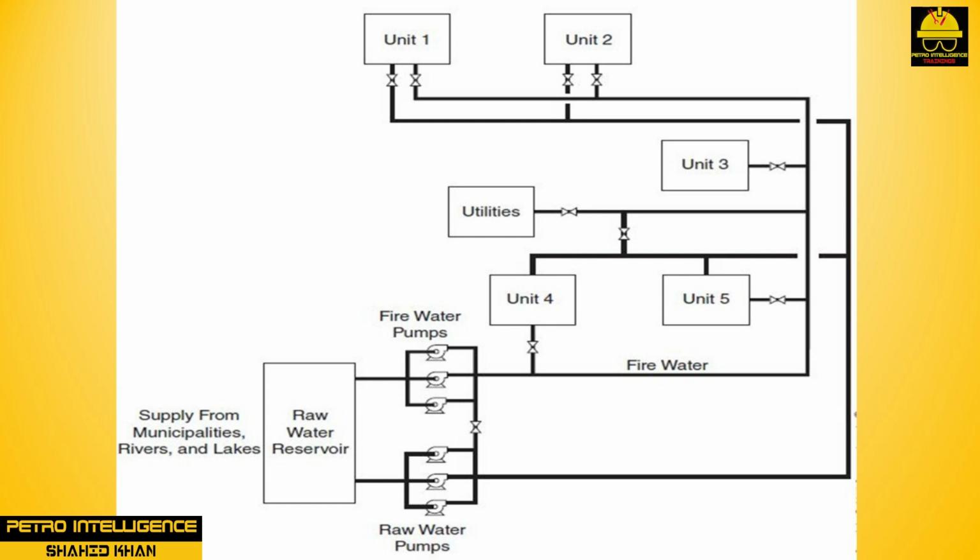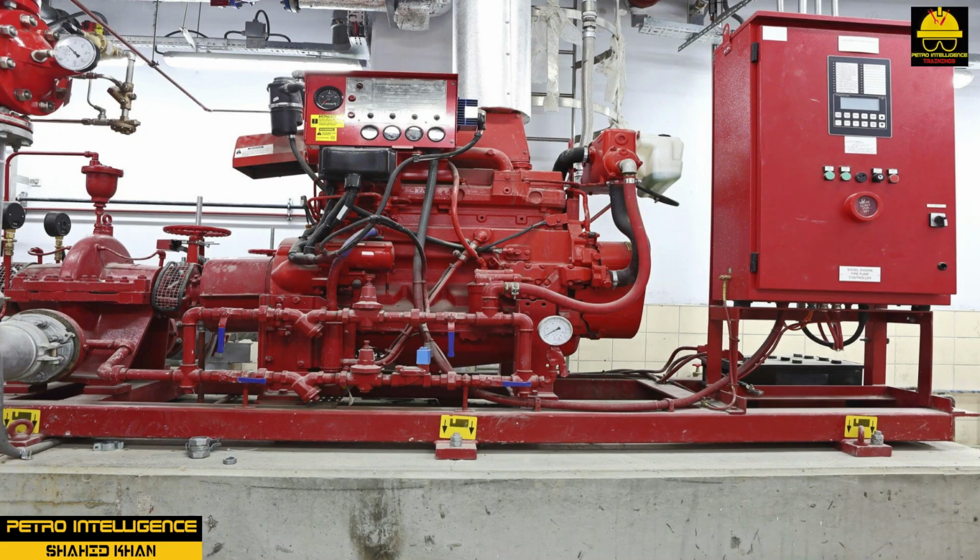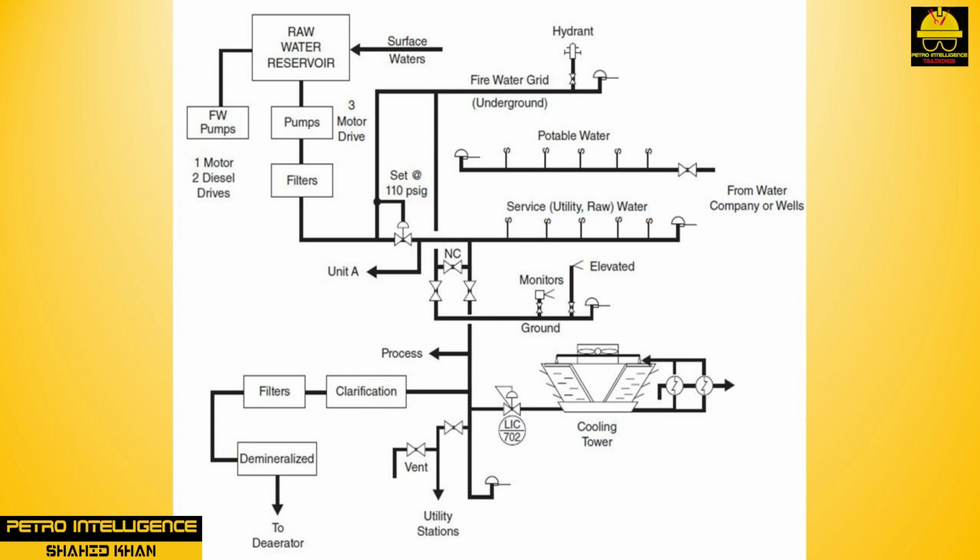Plants use raw water in utility station water hoses, process unit fire water, FW, hose reels, the cooling water supply, the supply to the fire water system, and boiler feed water makeup. Fire water is supplied to the plant by pumps, which must be capable of continuing to run if power to the plant is lost. These pumps are typically diesel-driven to ensure operation if electric power is lost. The FW system pressure can be supported by cross-connecting from the raw water system.